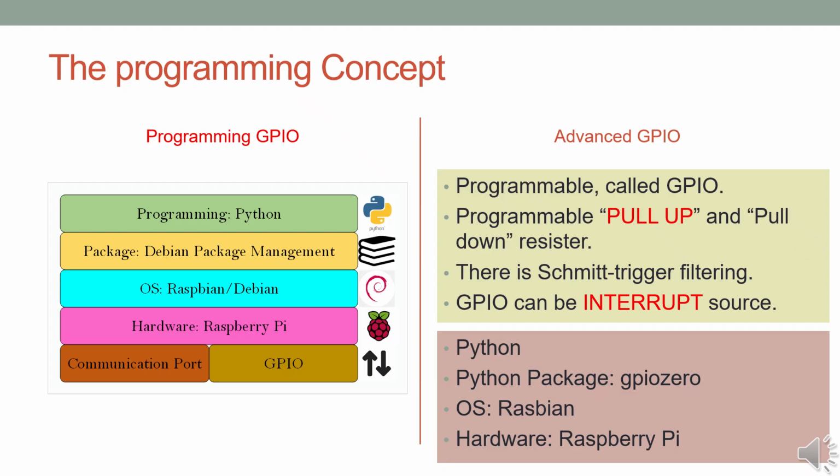The Raspberry Pi is equipped with powerful and versatile hardware, especially when it comes to external connectivity. It supports two main types of ports for external communication. Communication ports such as USB, WiFi, and Ethernet allow connection to peripherals and network devices. These are typical interfaces for microcomputers. GPIO ports, general purpose input/output, are more flexible and allow direct electrical connection to sensors, actuators, buttons, LEDs, and other hardware components. In today's session, our focus is on the GPIO ports, as they enable direct interfacing with external components at a low level.